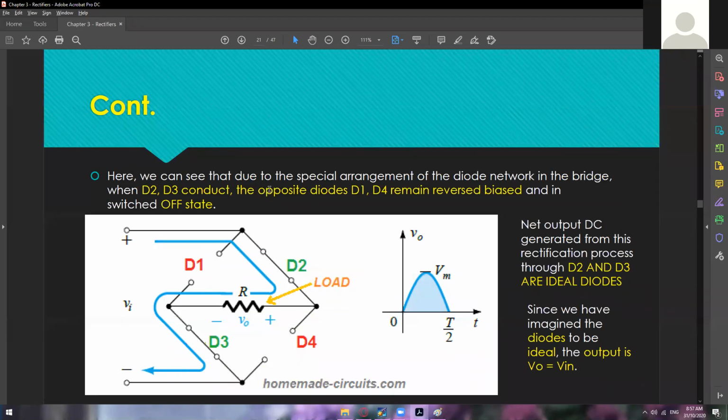Due to the special arrangement of the diode network in the bridge, when D2 and D3 conduct, the opposite D1 and D4 remain reverse biased and in a switched-off state. The net output DC is generated from this rectification process through D2 and D3, considering ideal diodes. If forward biased, it's a completely closed switch; if reverse biased, it's completely an open circuit. Since we imagine the diodes to be ideal, V sub O is equal to V sub I. Whatever the value of V sub I will be the same as V sub O, since we are not considering the threshold voltage of our diodes.